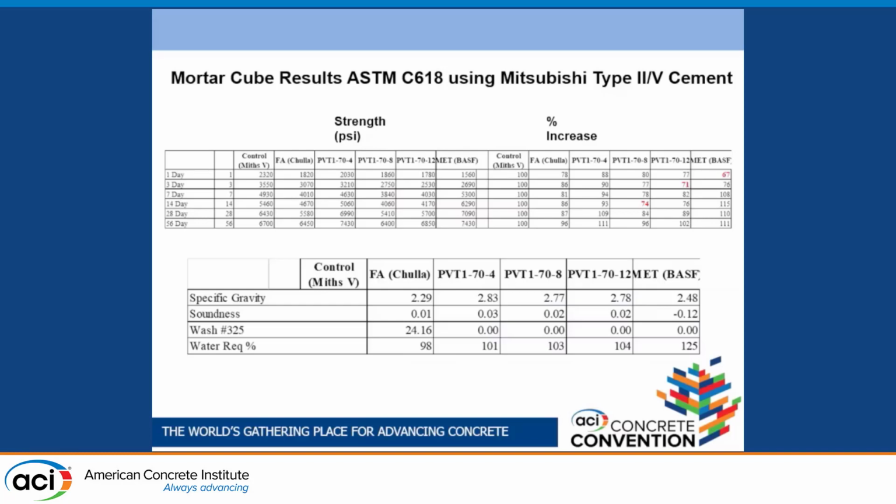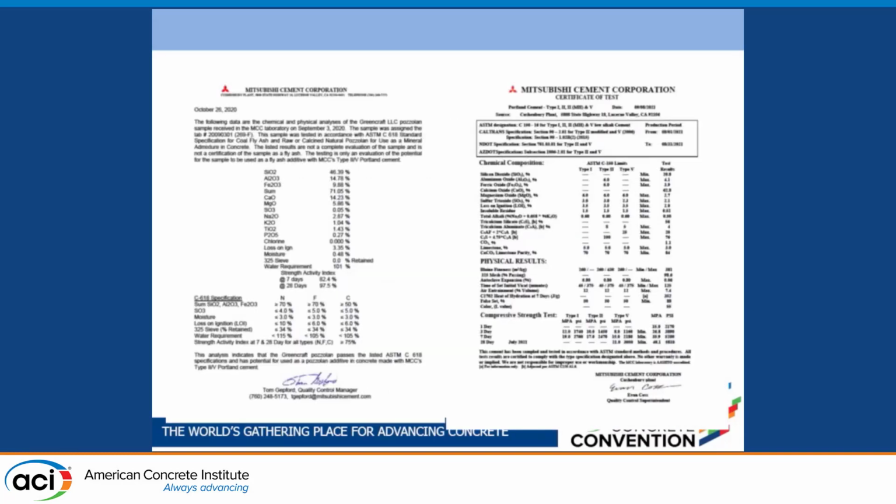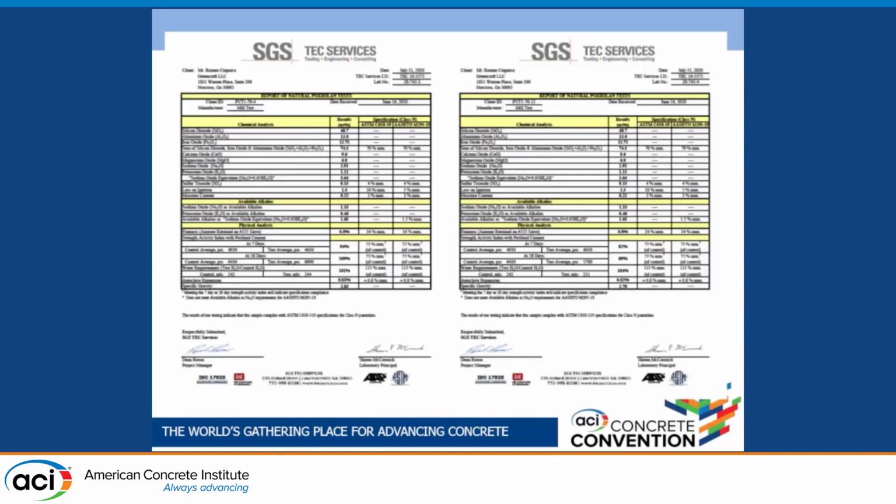In here, we were trying to determine what would be the optimal size to have, fly ash like, from a reactivity point of view. And we determined that to be around 12 micron D50. Those are the results plotted. So this is some other evaluation done by other people.